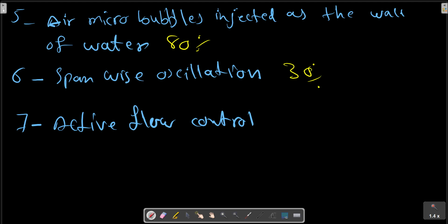As reviewed in various references, this method generally requires expenditure of energy but can be worth it. For example, tangential blowing at the rear of an auto evokes the Coanda effect, in which the separated near-wake flow attaches itself to the body surface and reduces auto drag up to 10%.